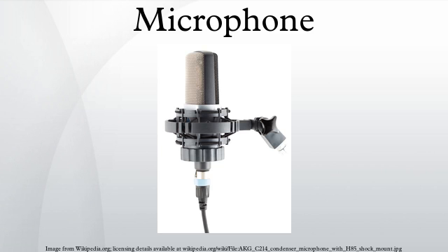The maximum SPL the microphone can accept is measured for particular values of total harmonic distortion, typically 0.5%. This amount of distortion is generally inaudible, so one can safely use the microphone at this SPL without harming the recording. Example: 142 dB SPL peak. The higher the value, the better, although microphones with a very high maximum SPL also have a higher self-noise.